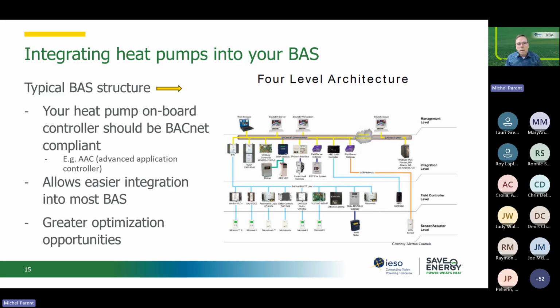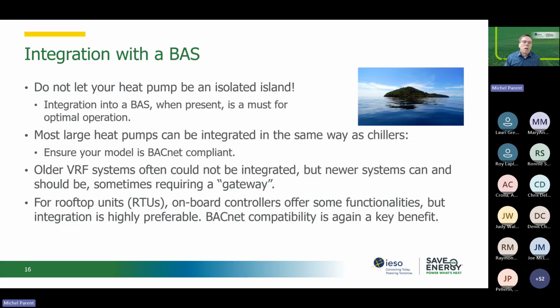The number of points you can get out of an AAC controller, and I'll show you an example, is really large. So you don't have to pay for multiple points on your heat pump if you've got a BACnet compliant controller. And like I said, it will reside on this field level controller. So you'll be able to find your panels. You see where it's going to connect. It's not a make or break, but it's really helpful to have a BACnet compliant AAC controller.